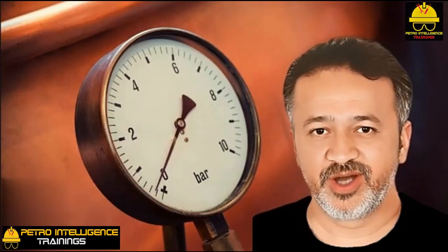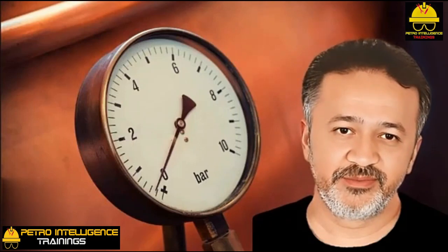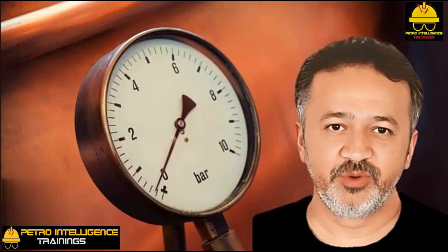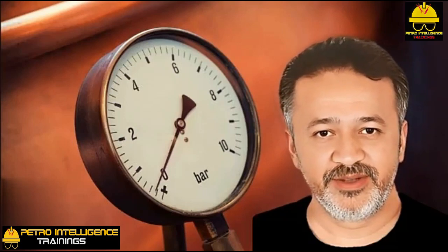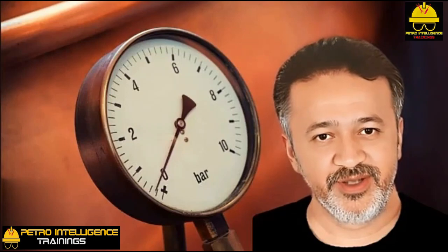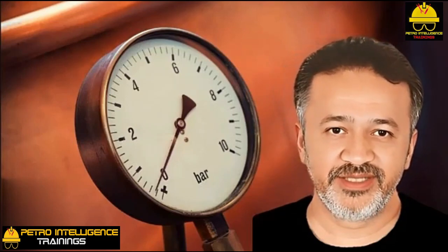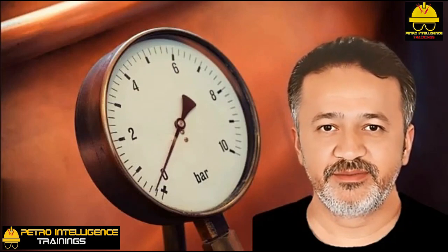Both the source of the slow neutrons and the receiver are located in the same box. The slow neutrons bounce off protons, hydrogen ions, and are reflected back. The rate at which these neutrons are reflected back is measured and corresponds to the hydrocarbon density in the vessel. This measurement is not affected by steel components inside or outside the vessel.